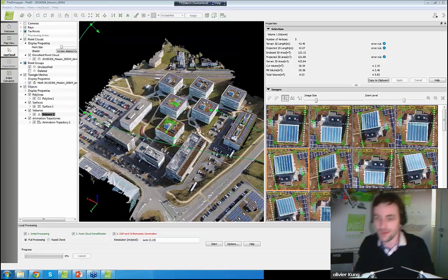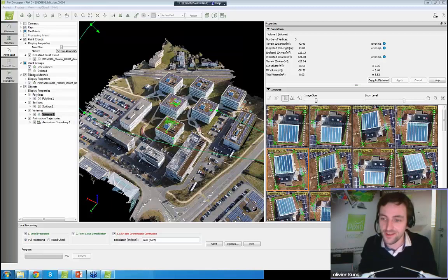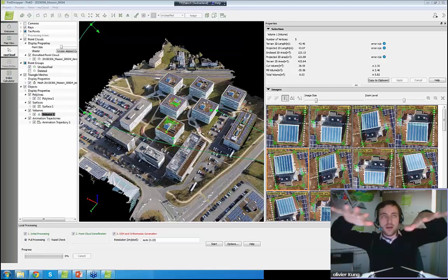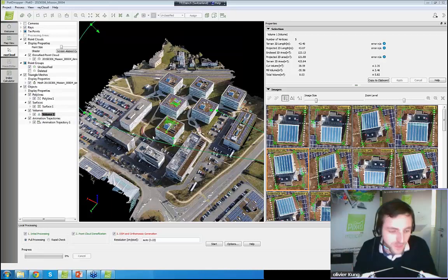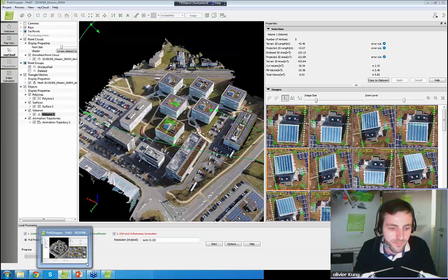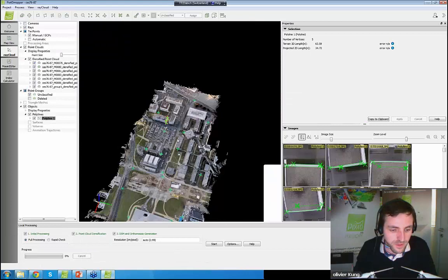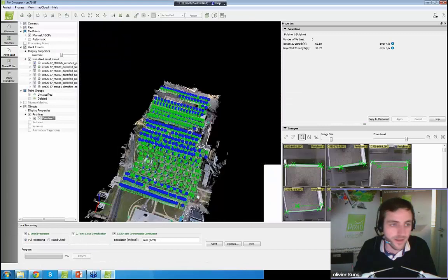How do you organize a survey in a bigger area than 200 by 120 meters in the field? To do that, I would suggest flying first with the maximum setting of the grid, get the grid, then you need a lot of batteries with your Phantom, and then you create a second grid just next to it. But I would strongly suggest, and maybe that's what you can see in the project that we have there, let me show this project. This is exactly what we did there. The area is much bigger here.